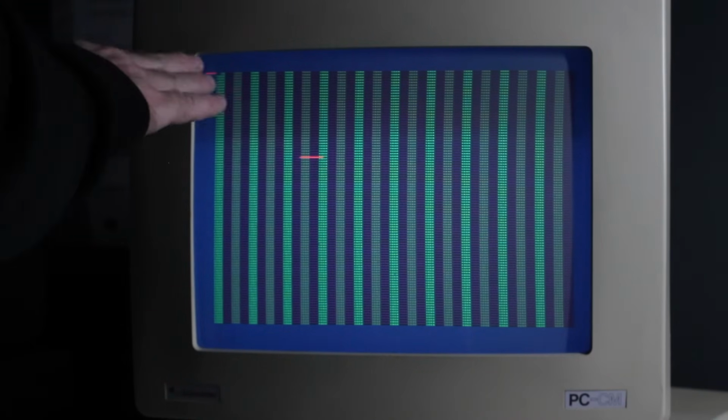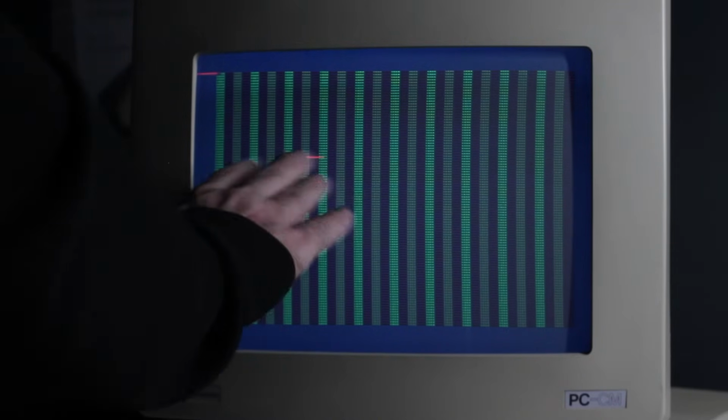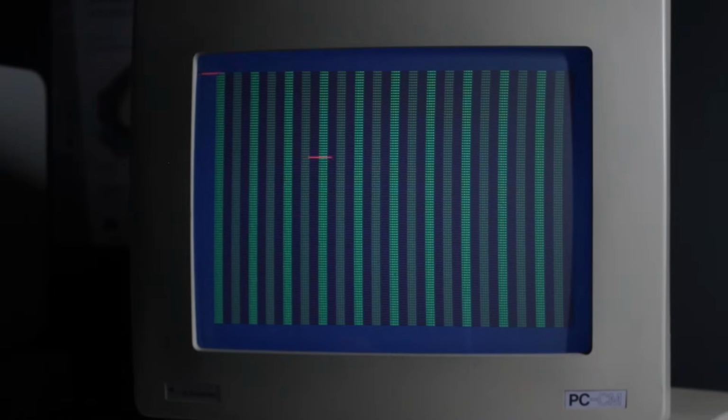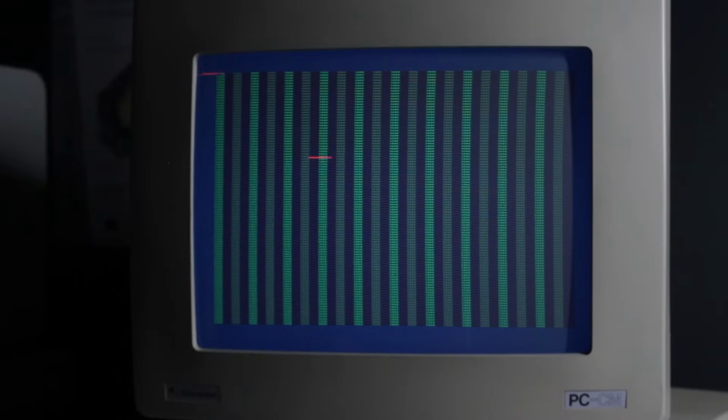So let's see what happens if I add an additional 4 CPU cycles. So move it right. That should move it a little bit more than 4 pixels to the right. Let's see what happens. Basically there was no change there, and if I press a key, so now it's actually shifting by about a character at a time. And it seems to me that basically something about these DRAM writes has to happen on a character boundary, which is really interesting.